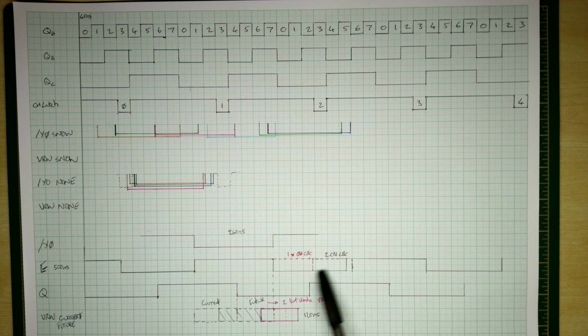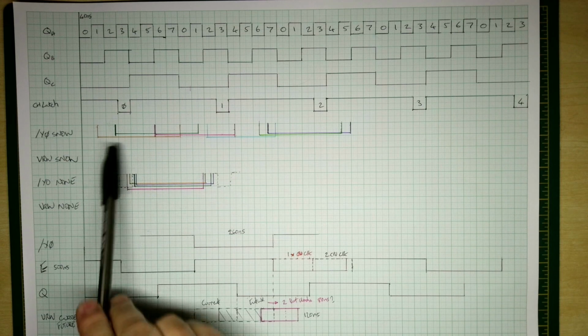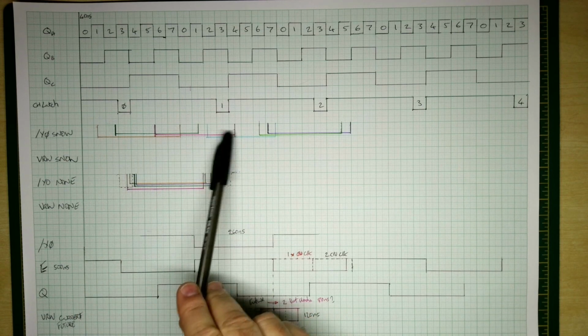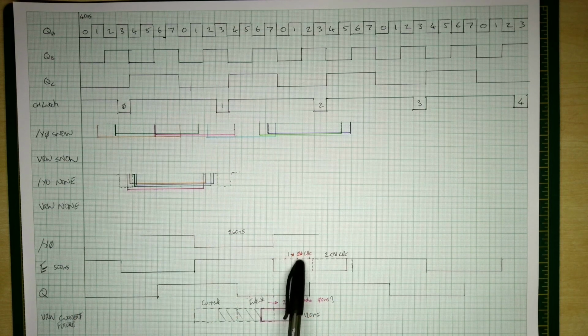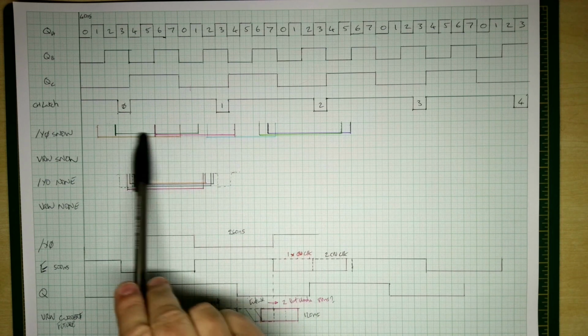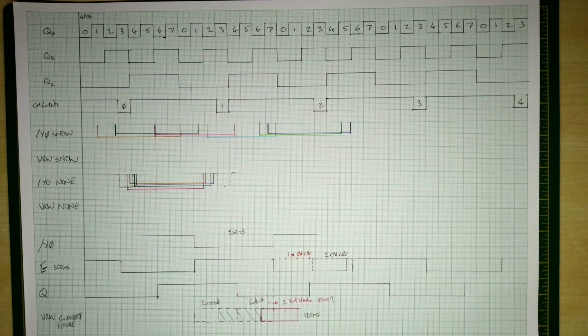And so what that might allow us to do, in circumstances where we're going to get this video snow, is add extra CPU clock cycles to move the period where we're accessing the video RAM to a period where we're not causing disturbance. Now at the moment, the Y0 signal is about 260 nanoseconds wide.